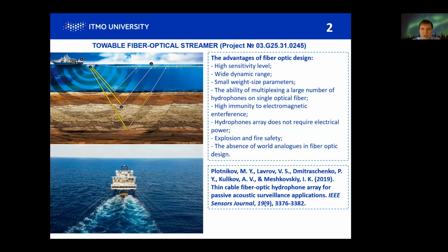Seismic streamers are usually used as acoustic signal receivers for geophysical and seismic surveys. Historically, the geophysical market has been occupied by piezoelectric streamers, which have a number of fundamental drawbacks: low sensitivity, high noise due to the inverse piezoelectric effect, high cost, and high weight and size parameters.